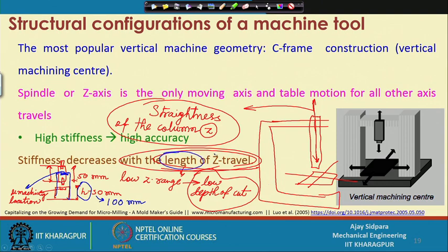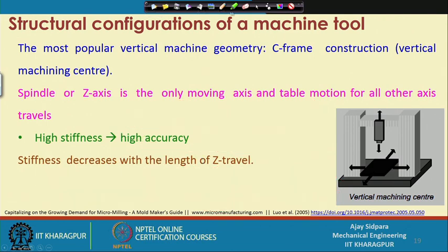That is the only reason, but our machining process or the machining depth will obviously be low. But when you are putting a big workpiece or a long height workpiece, at that time it is an issue, but that is not a problem every time. Sometimes you also have to think about what components you are planning to machine with this particular machine, and depending on that you have to design the Z axis.